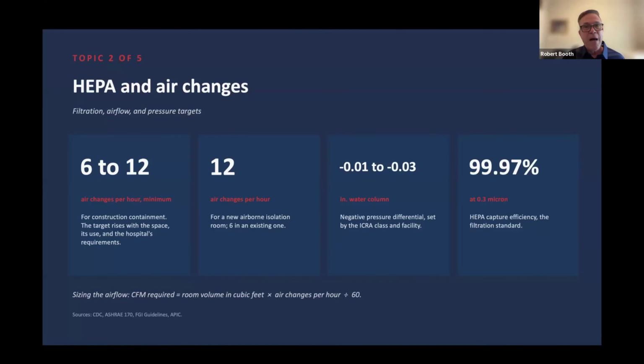One thing that I see a lot is when they change those filters out, they say, okay, we have HEPA filters here, but the device is really dirty, and then it doesn't pass the particulate sampling because contaminant got all into the device, and then it's going down the ductwork, and they really can't show that the particulates are reduced. So we ask that you clean that as well.